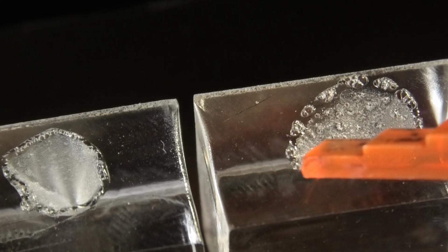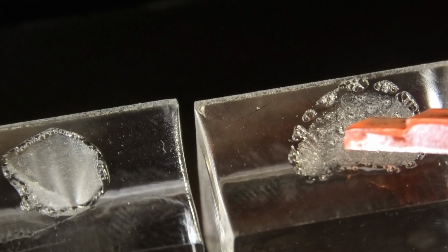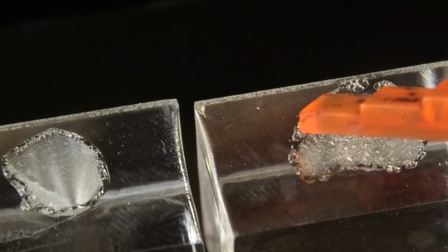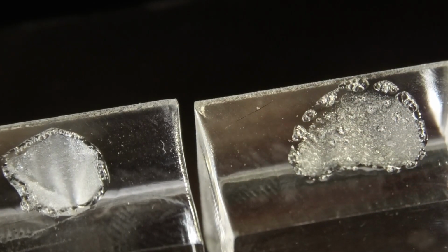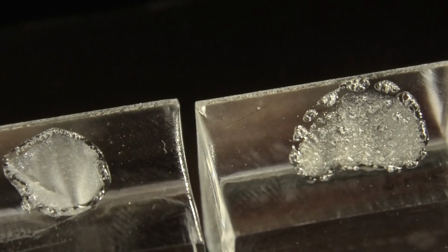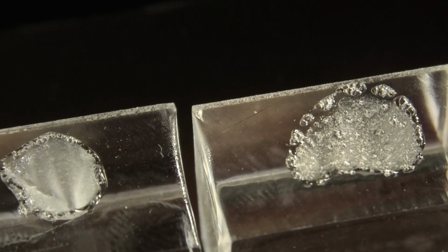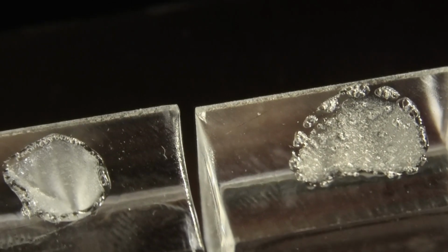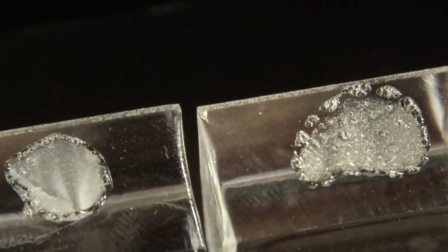We've got serious distortions. We can see that we've got little pulses of power there and a sort of central-ish power there, but look, we've got these marks around the outside here, these bubbles. Now, this is a particularly telltale piece of material, acrylic. It's a wonderful material for explaining how a laser tube works, or checking the performance of a laser tube and its power.